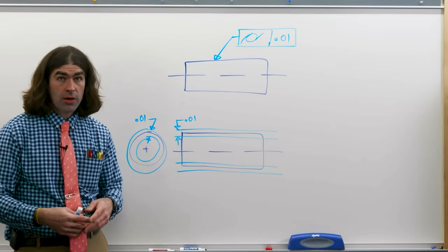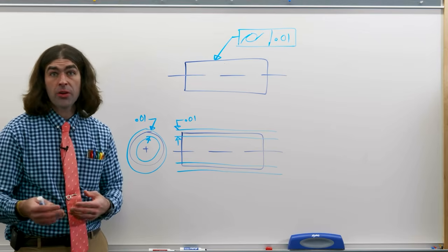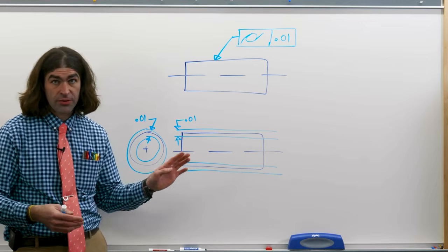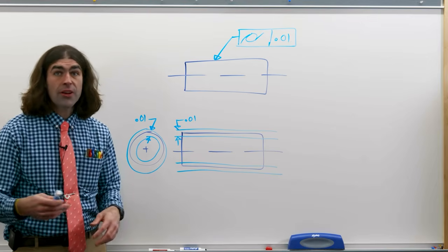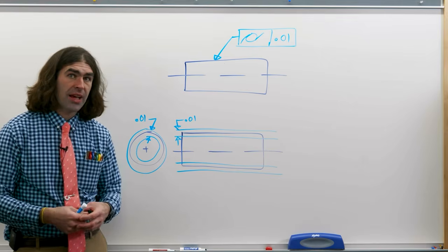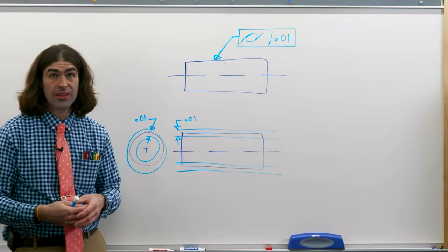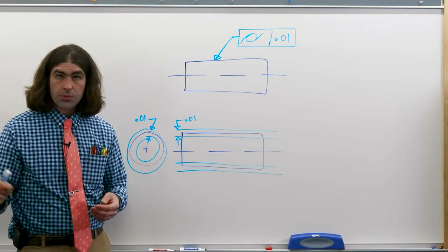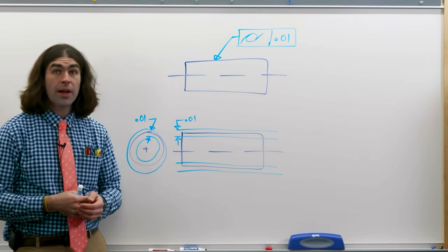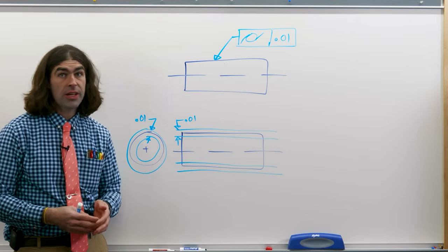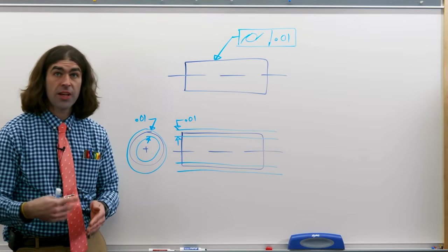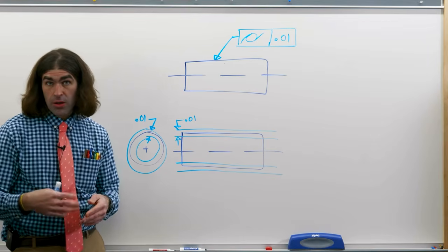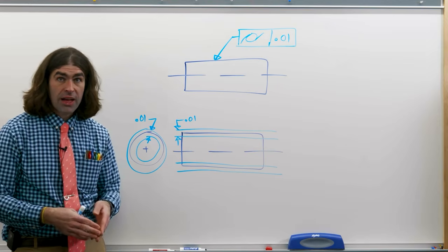Cylindricity can be used for cylinders that are primary datums, so you want to make sure your datum surface is nice and straight and circular. It's often used for things like hydraulic cylinders that have really exacting tolerances and need to be perfectly straight and circular to function correctly. And cylindricity only applies to cylinders, whereas circularity can be applied to a conical shape, a sphere, or a cylindrical shape. So that's it for a quick discussion of the 4 form tolerances.